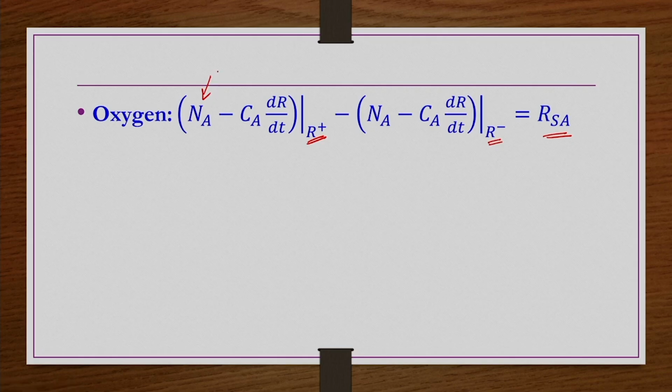So, at the surface we have already designated that quantities are provided with naught, Na, so Na naught, Nb, so Nb naught, like that. But this Ca, what should be Ca? The concentration of oxygen, it is coming with certain concentration and then reaching the particle surface, but moment it reaches the particle surface, immediately it is reacting and then carbon monoxide is forming. We are assuming that 100% oxygen is being consumed for the combustion with the carbon particle. So, then its concentration is 0, at the surface it is 0.